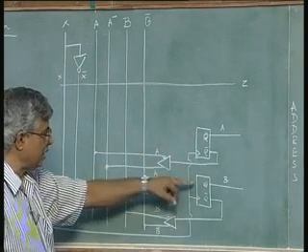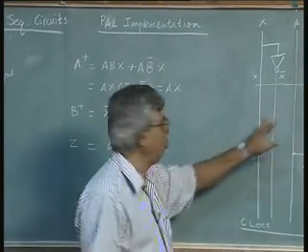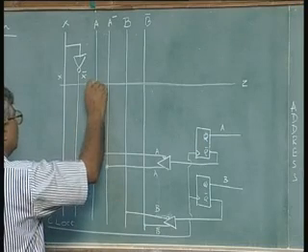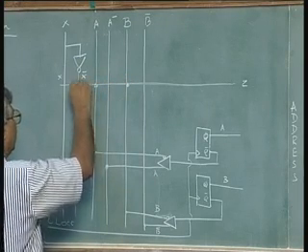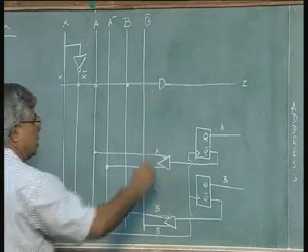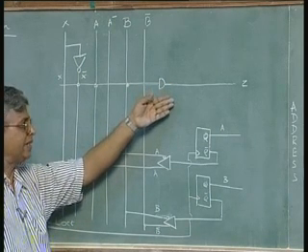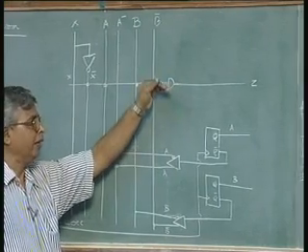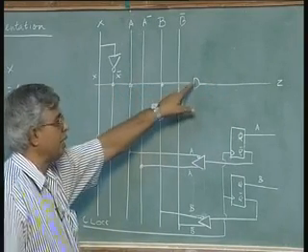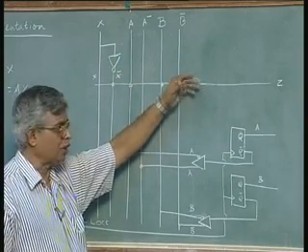Now all I have to do is to create the term for A plus, create the term for B plus, create the term for Z according to these equations using the combinational gates available. Z is very easy, it is A B X bar. So we have an AND gate. I am not going to show the actual way in which it is drawn in the book. This is enough. So we have a combinational gate. Of course, there will be several AND gates feeding to an OR gate, and you program it such that you get the output. But it is a symbolic representation. So I am going to combine this and this and this and get this requirement. This is only one of the several terms you can put into an OR gate.